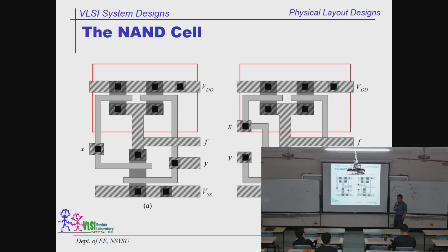And it is not appreciated in a high-speed design, because the longer the poly wire, the slower the speed, because the polysilicon is a high-resistance material. That means it's a big R. Big resistance is not appreciated. So that is why, when it comes to performance, it's not really appreciated in this kind of design.